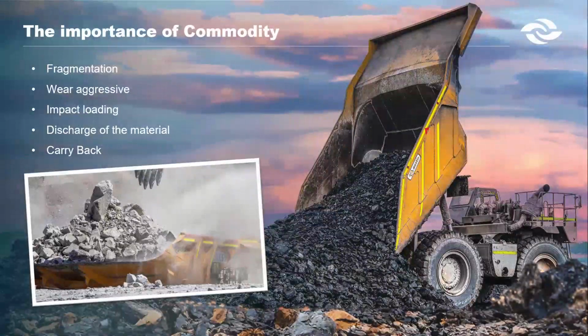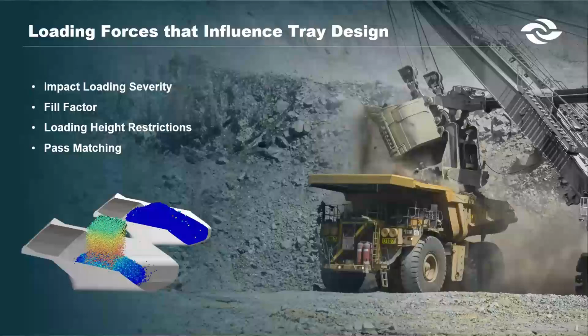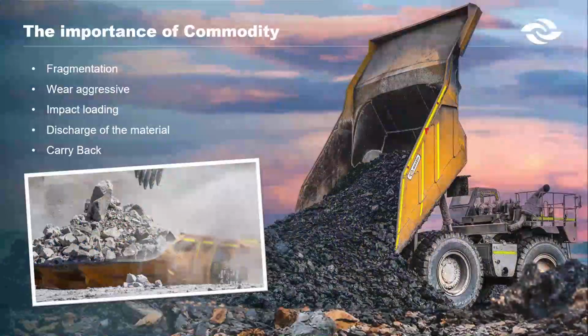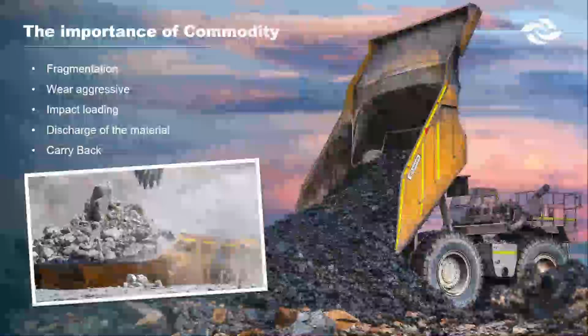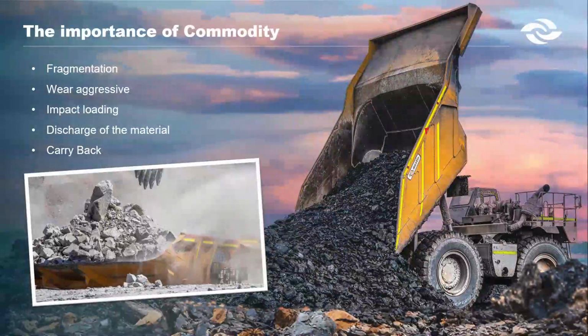Moving on to fragmentation, this also matters. Finer material flows like water, while blocky material impacts the floor like hammers. If the fragmentation is large, impact loading is severe, and the tray floor and walls must be reinforced accordingly.